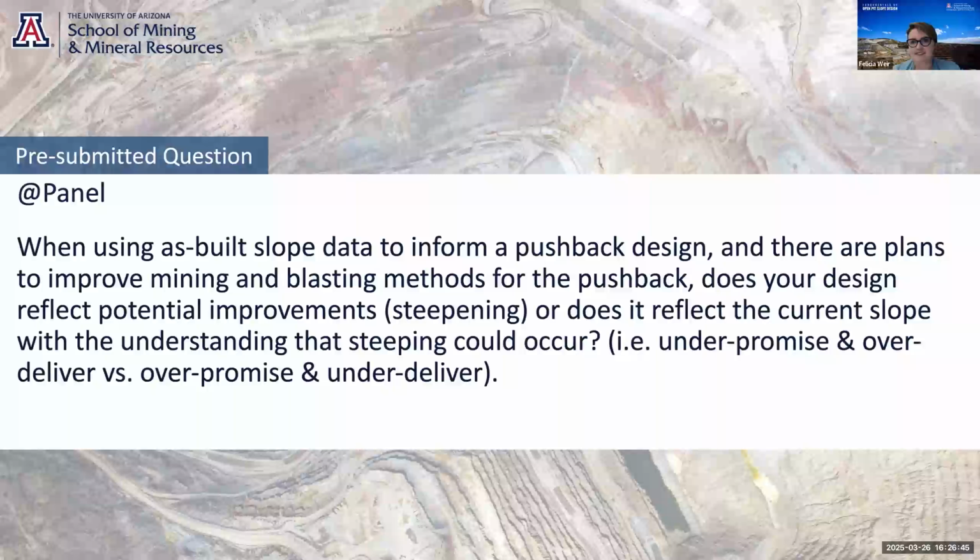I've been on a mine site where the mine planner will open up your design report and simply copy out the table, and then they close the report. And so they didn't note that you could only achieve this design if you're going to put in horizontal drain holes and do X, Y, Z. So if you're going to recommend a steeper design, you have to be very clear on what goes hand in hand with that in terms of operational constraints.